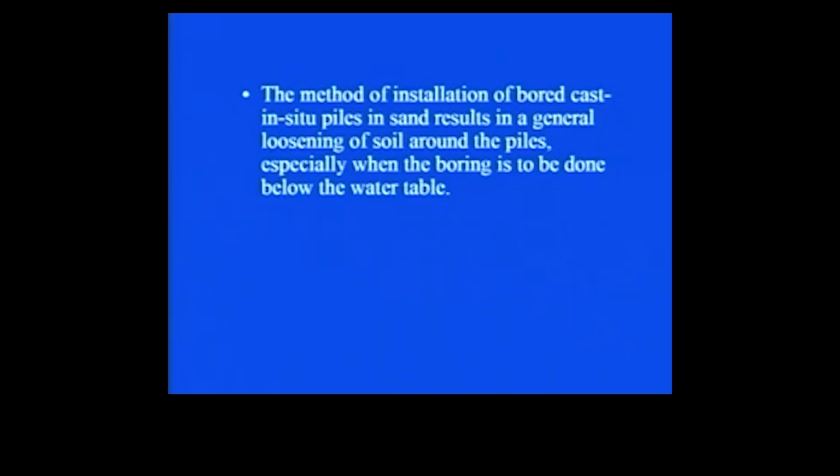The method of installation of bored cast in situ piles in sand results in a general loosening of soil around the piles, especially when the boring is to be done below the water table.